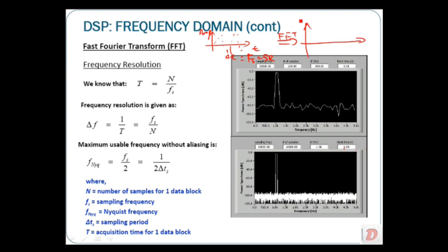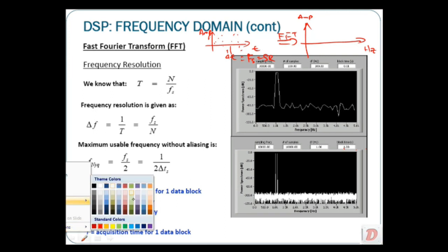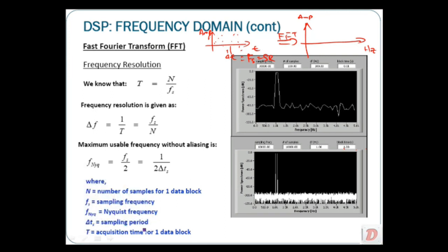All right. Through FFT, your signal in amplitude over time is represented in amplitude over frequency in hertz. The discrete FFT is a discrete type of Fourier transform. You need to decide how many samples you want to convert to the frequency domain. This is defined by the number of samples, or block size, because it is processed by number of samples.